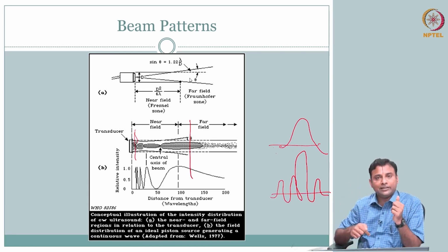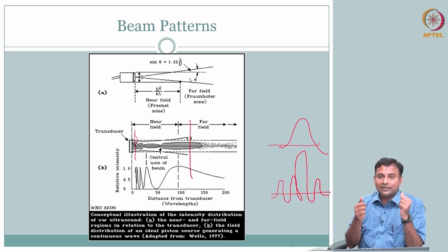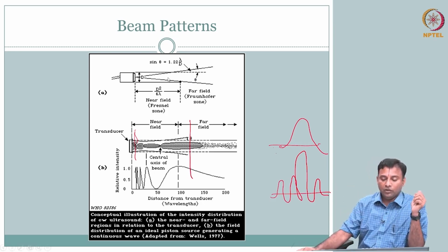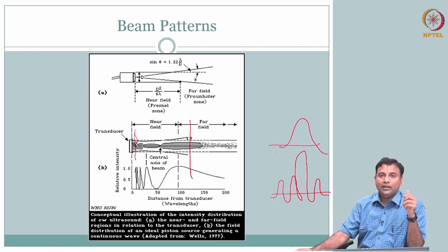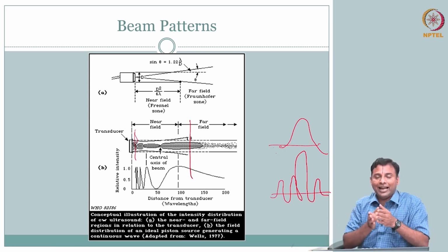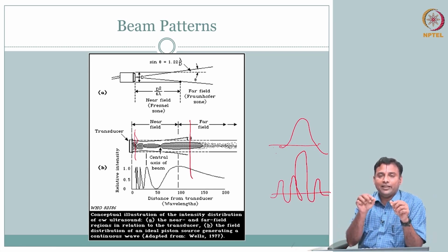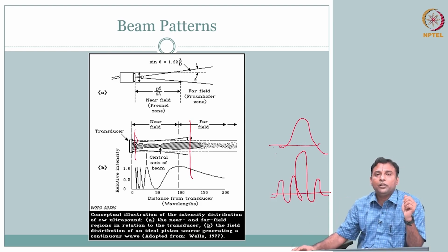The axial direction is fine where the high frequency wave is going, but the lateral is related to your beam width. So, we should be able to know what this divergence is. Divergence is not good, because you are loosening up your lateral direction. If you have a point, it will spread more in the lateral direction. Point spread is going to relate to both your contrast and your resolution per se.